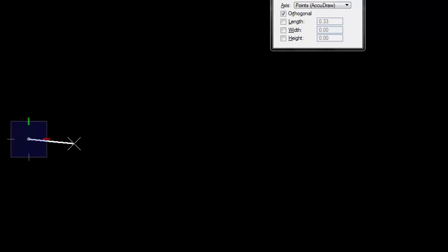So let's say I want a slab that's 2 inches by 4 inches by 1 inch tall. If I just left click on the screen, you'll notice I get my normal view oriented compass. Now keep these letters in mind, and I use an acronym. I forgot the acronym now, but we use F for front, T for top, S for side. I know it is SOFT V, SFT, and I put the O in there just because that's our origin key, remember. So SOFT, think of the word soft, and then V for view rotation.